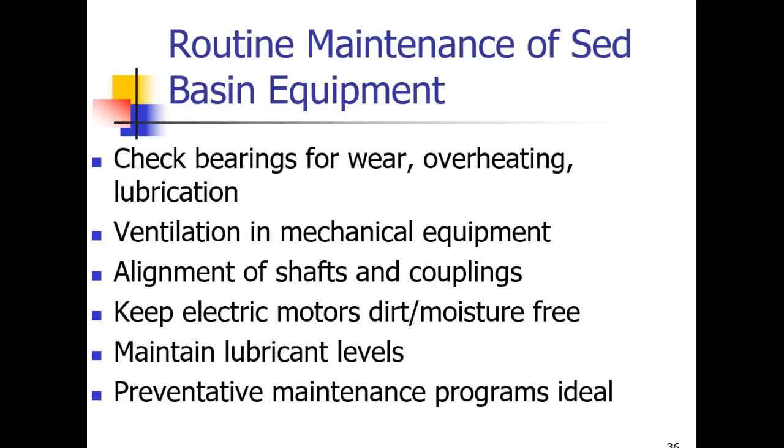Routine maintenance of sedimentation basins and equipment. Check your bearings for wear, overheating, and lubrication. Ventilation and mechanical equipment. You always want to make sure your equipment has ventilation. If you put a pump into a closed closet, it's going to heat up in there. Check the alignment of shafts and couplings. Keep electric motors dirt-free and moisture-free.